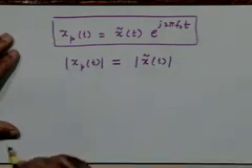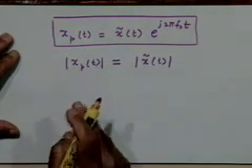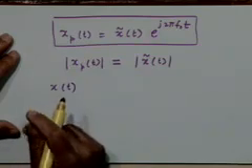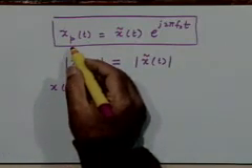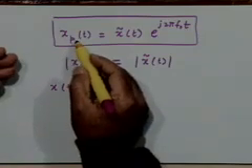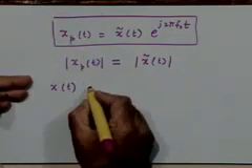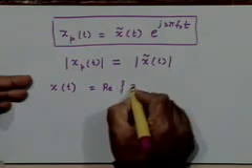Right. Now let's proceed a little further. My final purpose is to express x of t, the original bandpass signal, in similar terms, right? Because what I have got right now is a representation not for x of t but for the analytic version of x of t. Suppose I want to go from here to x of t. What should I do? I should take the real part of the signal, right? X of t is real part of xpt.